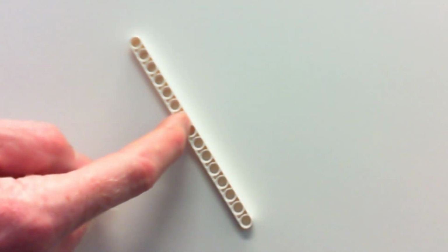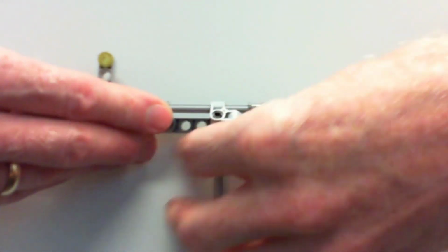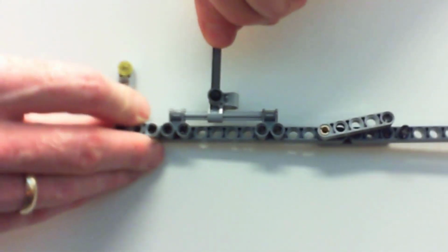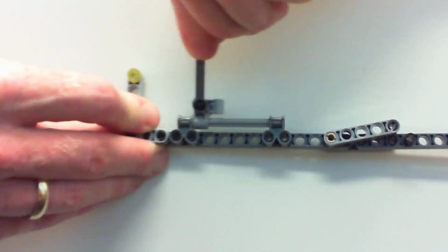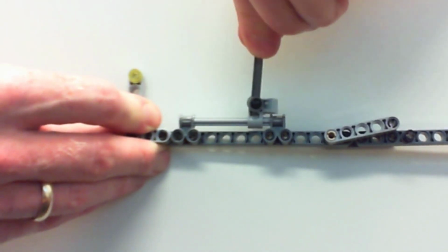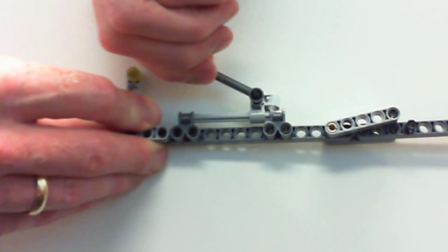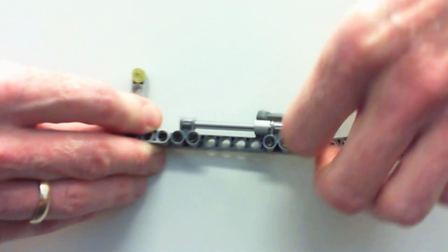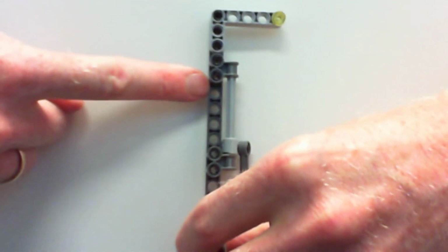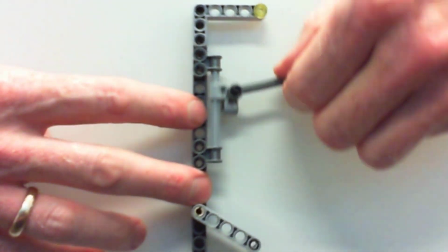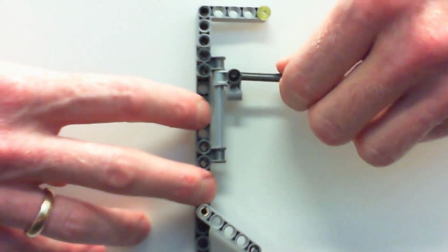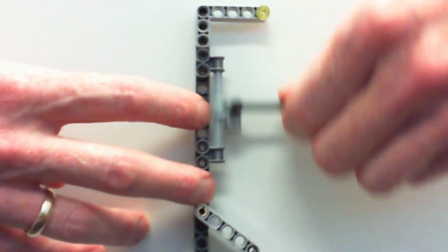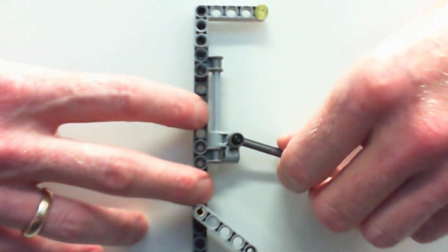Now we're assuming that the rocker can essentially go back and forth, but it is still providing a normal force perpendicular to the surface. Another one that we have is a collar on a smooth rod. So here is a little demonstration of that one. Ignore the pieces out to the right and left, but essentially here we have a smooth rod. It can slide back and forth. It doesn't matter what angle the member comes in, there's always going to be a force perpendicular to the rod. And so if the rod is vertical, that force is horizontal. And so all of these, once again, are normal forces.